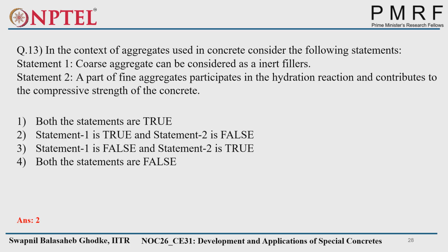I hope you remember we take one beaker, we pour the sand in that and water, and we keep it for some time to identify it. No, no, bulking is different. That we used to find out only silt content. What is the amount of dust available in that? So yeah, like that only. We will call that the silt test.